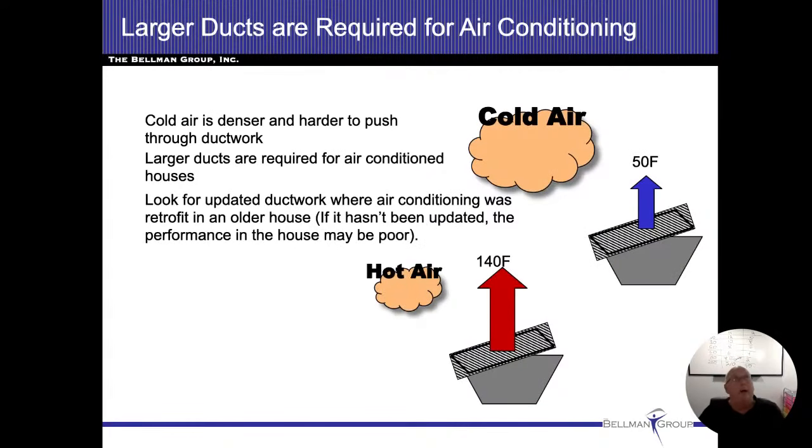Larger ducts required for air conditioning systems. We kind of talked about that earlier. There's always a plan B. So if I have a stronger fan, I can go ahead and get that airflow through it as well. So when we check our ductwork, we like to check it for both air conditioning and for heat at the same time.